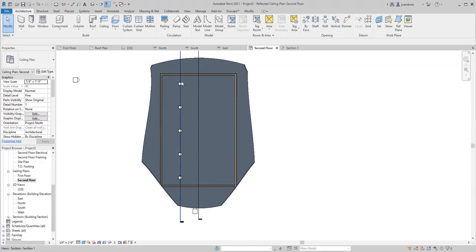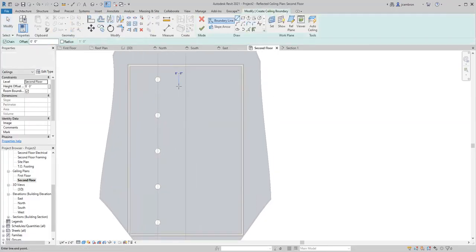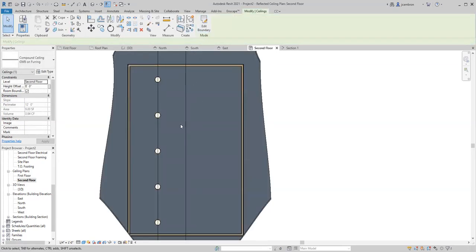before actually hiding all of your ceiling lights, right? Because once you hide them, if I was to go in and try to create a new ceiling and go through the same process, oops, let's use a rectangle. Hit the check mark. I don't see it. And I don't see it because we had told Revit to hide all of my ceilings.